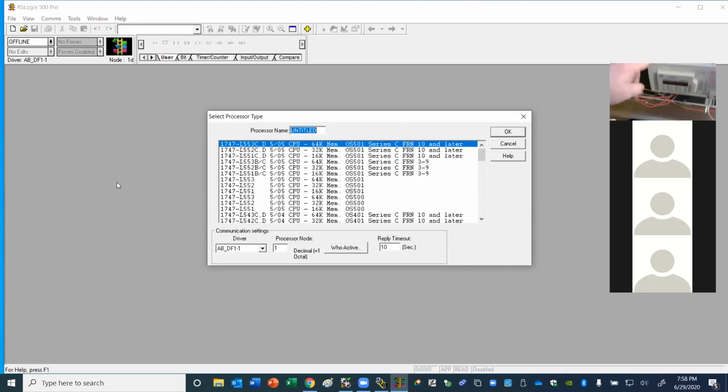What you've got is a PLC with fixed inputs and outputs with no additional modules. It has 12 inputs and 12 outputs. But the CPU can slide out this way, and then we can see the part number, the catalog number, once we get the CPU out. So let me move something here so I can do that, and hopefully get where I can see this on a large screen. Yeah, that's better.